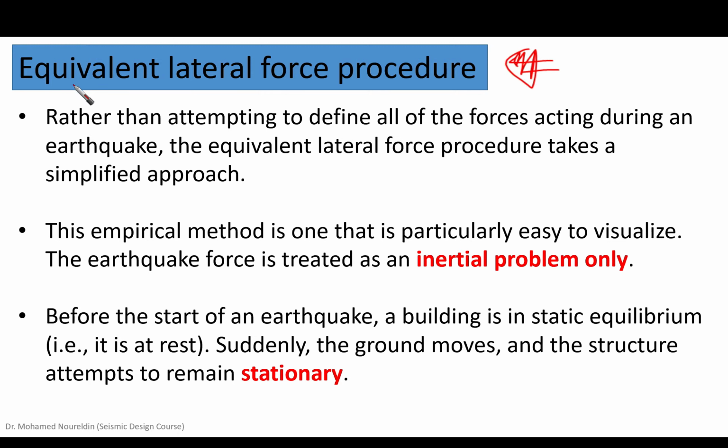We are going to use the equivalent lateral force procedure. Rather than attempting to define all the forces during an earthquake, as we said before, the equivalent lateral force procedure takes a simplified approach, and this is the most simplified approach. What is the rationale behind the equivalent lateral force method? The empirical method is one that is particularly easy to visualize. The earthquake force is treated as an inertia problem only.